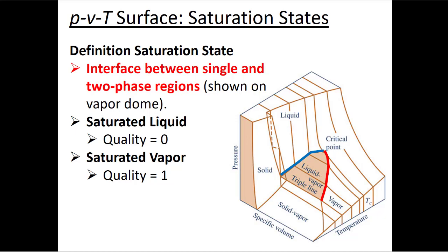And if you put in just a little bit more heat, you'll start to break apart those water molecules so that they're further spaced, and you have some amount of steam or water vapor and some amount of liquid. But as you're just getting to that point, you'll have all the water as a liquid at this saturation temperature. So your quality will be 0.